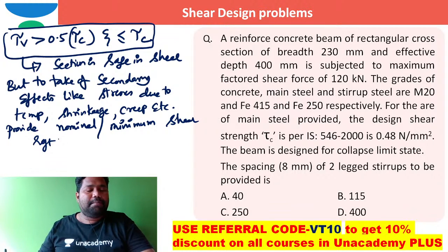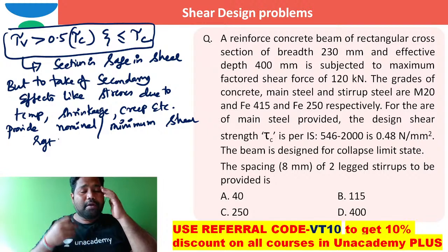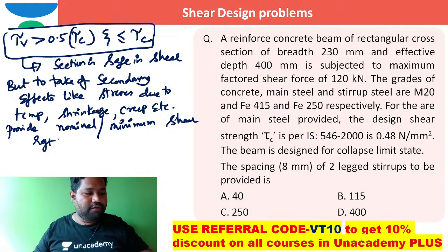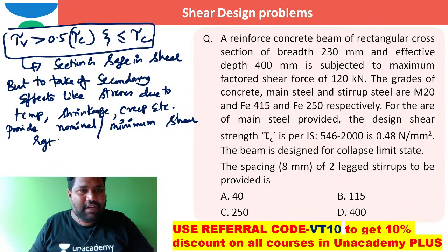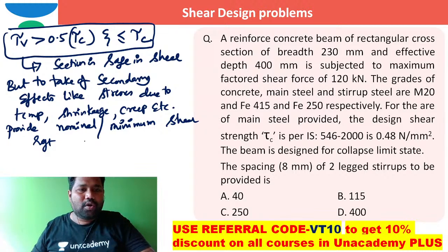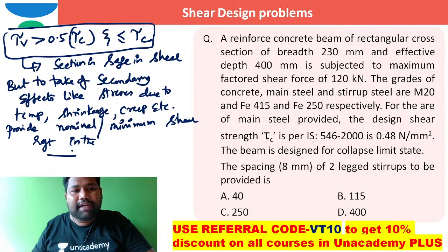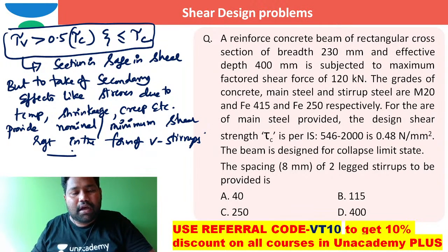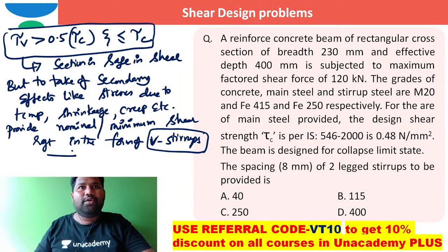Some people will ask, sir, how to provide this minimum shear reinforcement? The code says you need to provide the shear reinforcement in the form of vertical stirrups only, because vertical stirrups are more stable when compared to inclined stirrups.